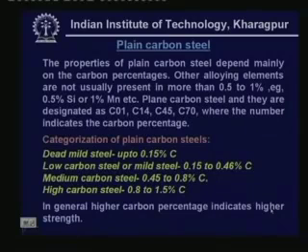So the higher the carbon percentage you go for, the more strength and hardness it has. In general, higher carbon percent indicates higher strength. And as I told you, these plain carbon steels are used in a wide range of machine elements.